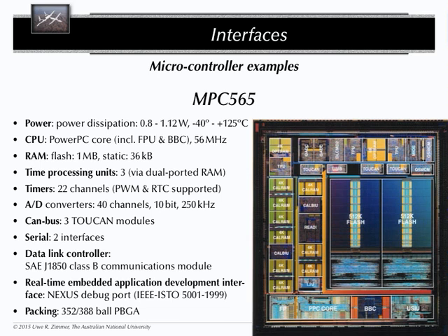What have you done in the past to debug a system like this? How would you, from a hardware perspective, engineers to the front? Logic analyzer, yes, exactly. And it's a pretty beefy logic analyzer because you have a lot of pins on that thing. And this is pretty much what it looked like. They called it inline emulation, which means they ripped the microcontroller out of its socket when these things were still having a socket. These days, of course, they aren't.